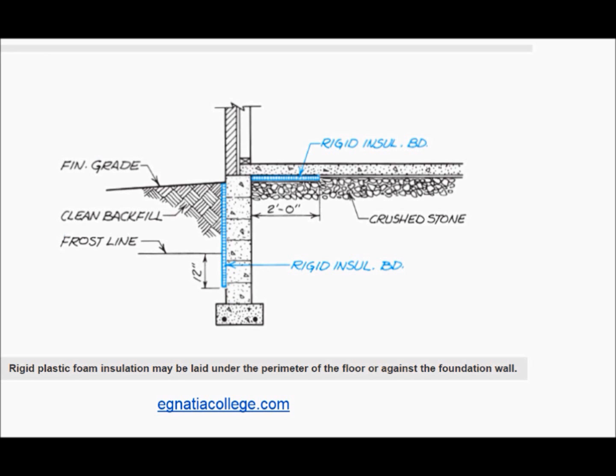superstructure is framed. The weight and rigidity of the floor on the foundation wall help the wall to resist the pressure of the backfill. If the backfilling must be done before the framing, the foundation walls should be braced.